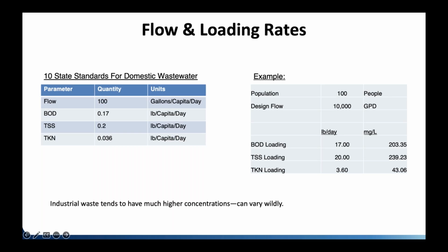So that's you going about your daily business. That's you going to the bathroom, washing your hands, washing the dishes, turning on your dishwasher, whatever. It's going to be about 100 gallons per person per day. Truth is, that's a little high, but in the engineering world, we love to be conservative. So that's what we are.